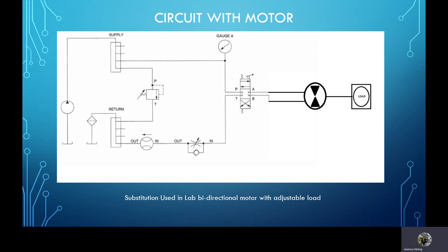So this kind of proves the point that we went from pretty much minimum pressure to maximum pressure on the system, and we were still able to move the load pretty much throughout the pressure dynamic. I mean, once we cranked it down, we were able to stall the motor at a low system pressure.